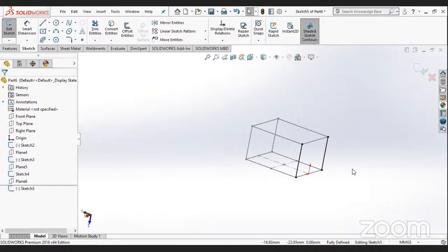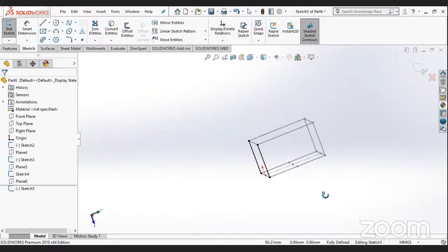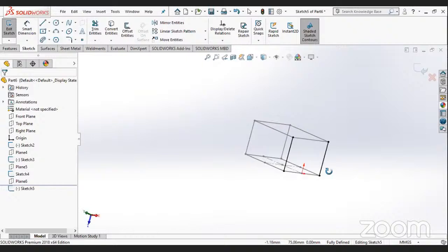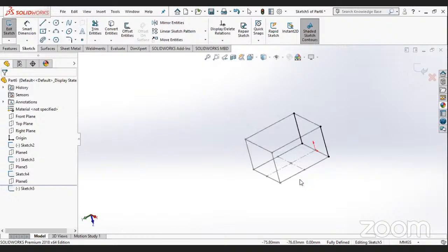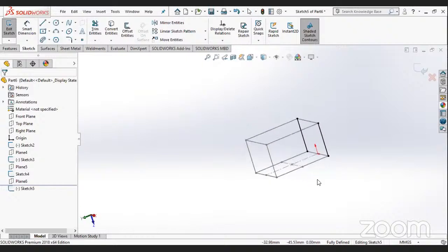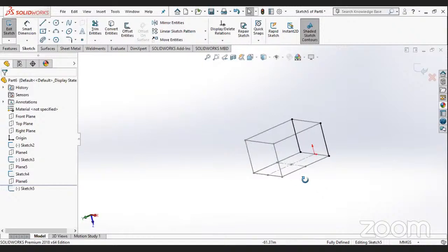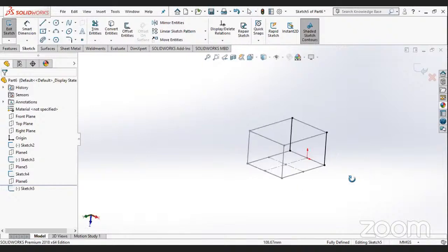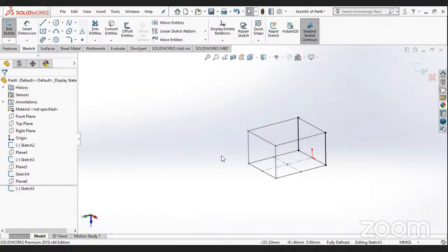After making this line diagram and finishing with the planes, I'll show you how you can apply some kind of material to this line diagram. You can see that we cannot extrude this as it is a 3D line diagram. So if you want to apply different kinds of materials like square, circle, bars, or anything, there's a feature here called weldments.